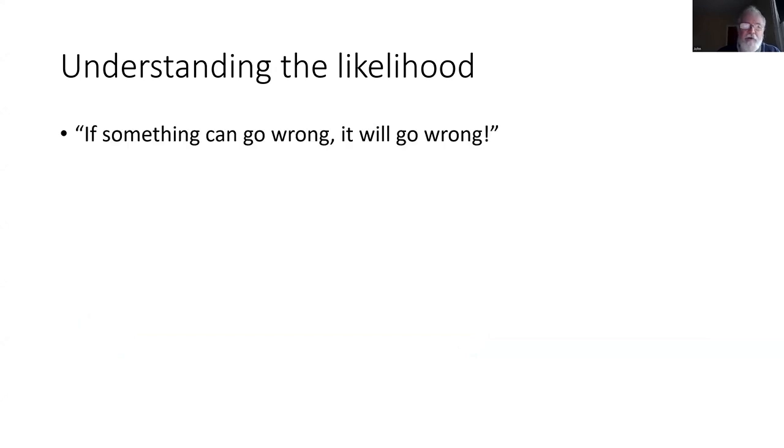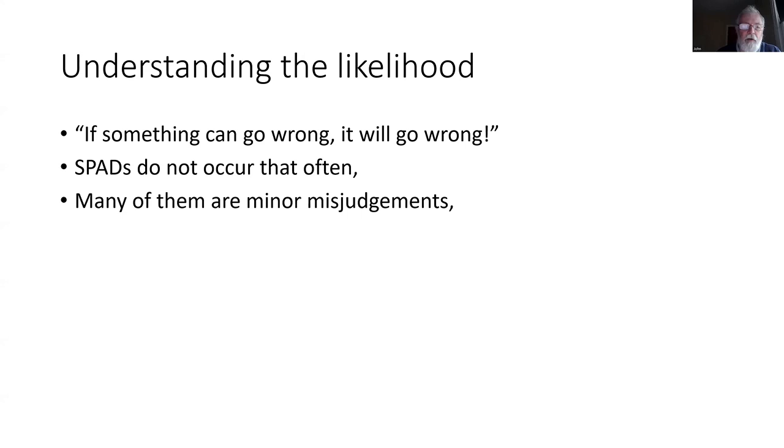Now, one of the issues was trying to understand how likely SPADs were and also how likely it was that any particular train that did SPAD would reach a point of conflict. And we always know that if something can go wrong, it will go wrong at some point. However, we're looking at a large number of trains and a large number of approaches to a red signal. And thankfully, SPADs do not occur that often. We are grateful that the drivers are generally conscientious. Many of the SPADs that do occur are actually only minor misjudgments of braking and result in an overrun distance of a few meters.